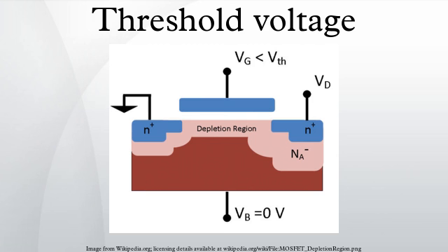Dependence on temperature. As with the case of oxide thickness affecting threshold voltage, temperature has an effect on the threshold voltage of a CMOS device. Expanding on part of the equation in the body effect section, where k is Boltzmann's constant, T is temperature, q is the charge of an electron, NA is a doping parameter and ni is the intrinsic doping parameter for the substrate. We see that the surface potential has a direct relationship with the temperature.